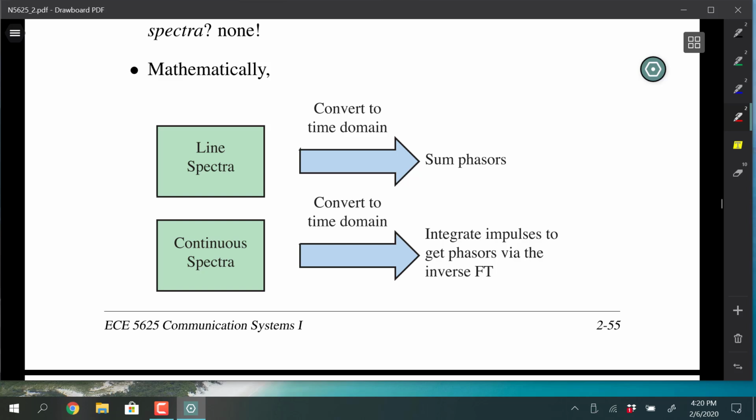So as the oscillator sweeps along, it's just taking all of those signals that are at high frequencies, and as they individually convert through the difference frequency down to 0 as you sweep on through, those get detected and create a deflection on the display, and the axis of the display is following the action of the sweep generator. And then you're controlling the bandwidth of what you see through the resolution bandwidth, which is the bandwidth of the video, and so on. That kind of makes sense?